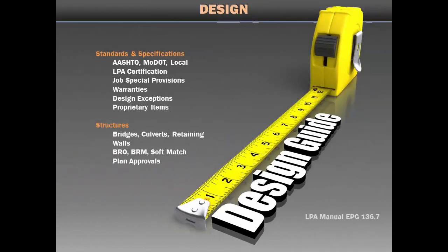For structural design, we are going to discuss a couple main focus areas. The purpose of the Federal Aid Bridge Program is to reduce deficient bridges. There's a list of eligible off-system and on-system structures on the LPA website that list whether a bridge is partially or fully eligible. If a project is partially funded, then it is only eligible for a rehabilitation instead of a replacement. Structural repairs must have at least a 25-year lifespan, no maintenance band-aids.